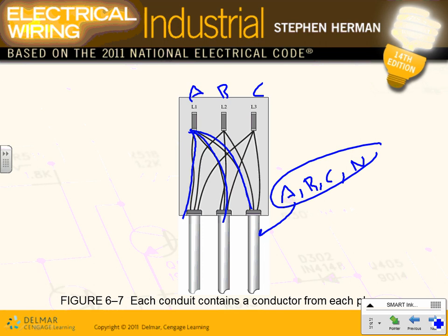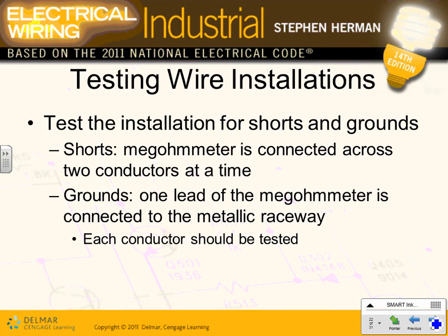When I parallel, can I put the conductors of phase A all in one conduit? Anybody? No, except if you're using PVC. If you're using PVC, then there's no inductive heat. But typically it's not practiced though.